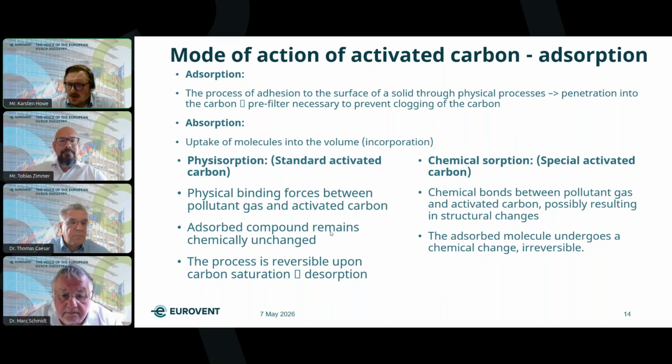What is to tell, you have a high variability for the activated carbon and a significant difference in the separation efficiency depending on the medium. So that means there is no single type of coal that is best for all applications. It must be selected based on the specific pollutant, and different kinds of coal can also be combined.